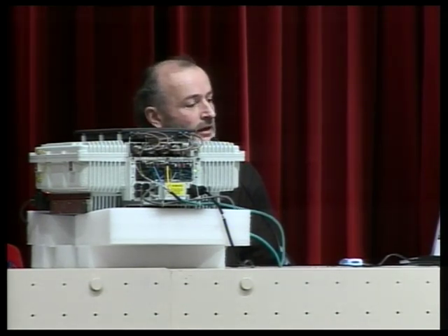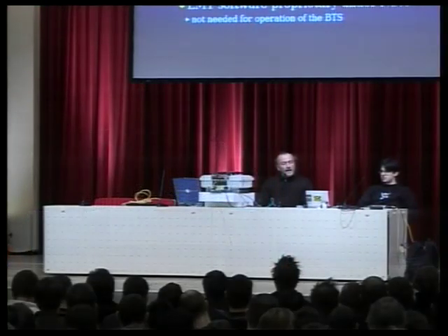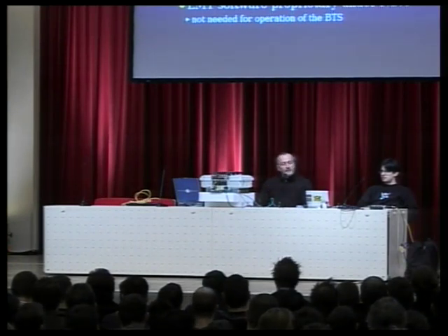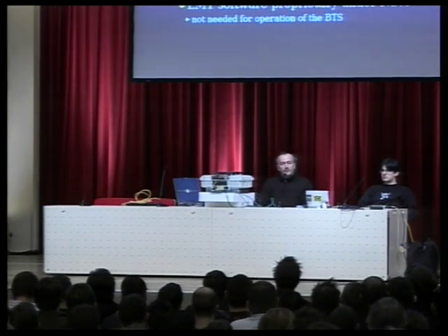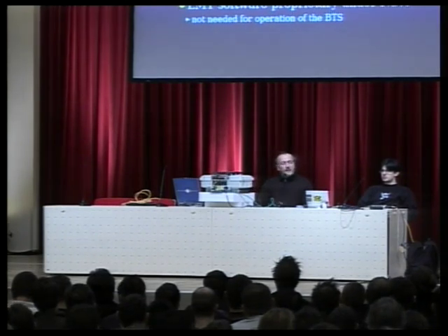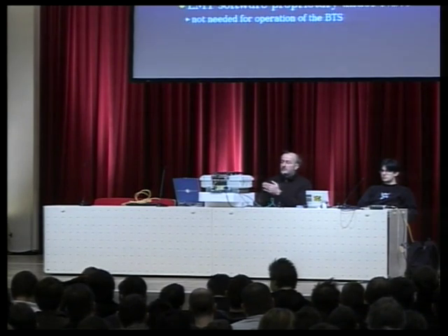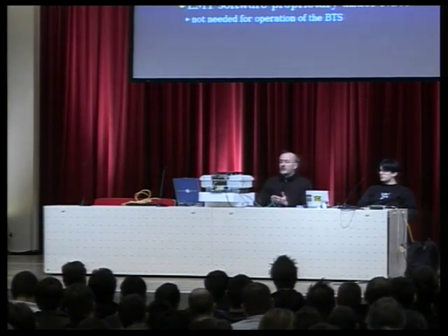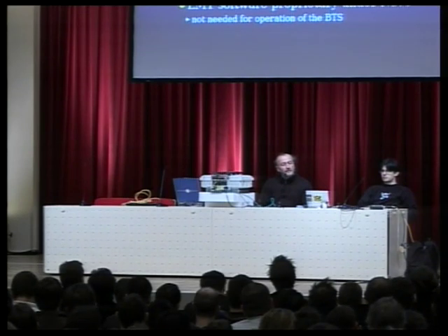Okay, the interface. In our case, to our software, the base station controller, this is going over an ISDN interface, and the base station transceiver has 2 ISDN interfaces. We use one to connect it to our base station controller, and currently the second one is not used, but it could be used to daisy chain several base stations. We have a lot of time slots on our ISDN channel 31, and if we support all the capabilities of the base station, we would only need 3 or 4 time slots at all. So we have several spare ones which we could use for other base stations which are daisy chained over the second ISDN E1 interface.